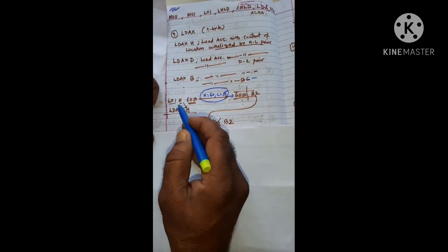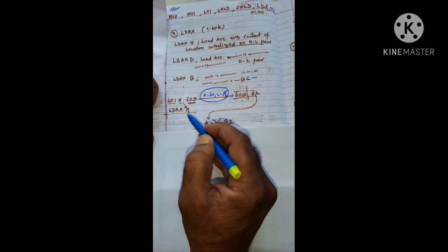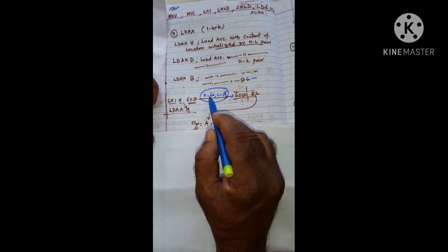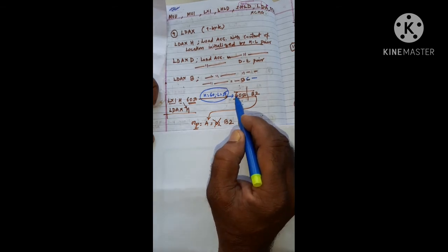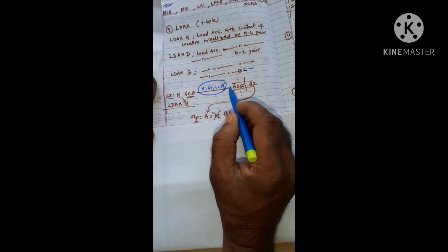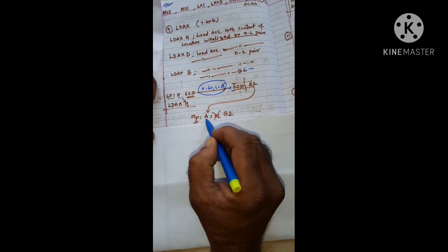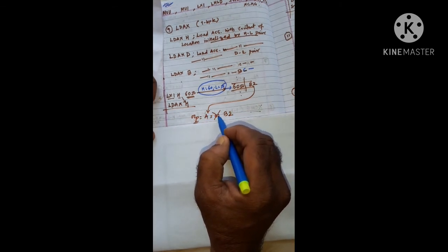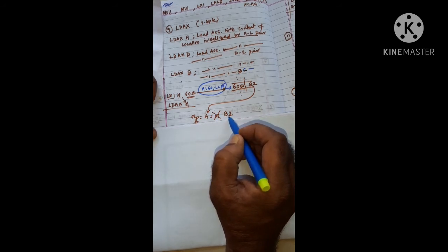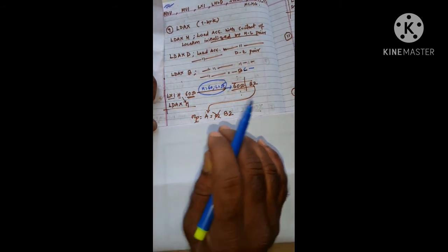After this instruction, if I use LDAX H, here H means the HL pair should be used. So the location initialized by the HL pair is 6050, and the accumulator is loaded with the content of that location. This B2 content will be shifted to the accumulator. If the previous content of A was 01, the new content will be B2 after execution of these two instructions. Clear to you?